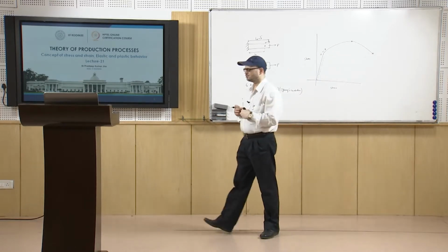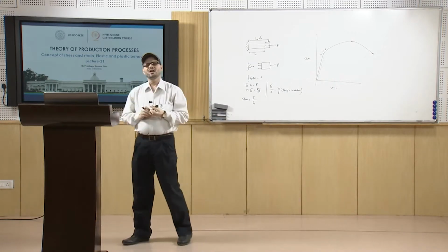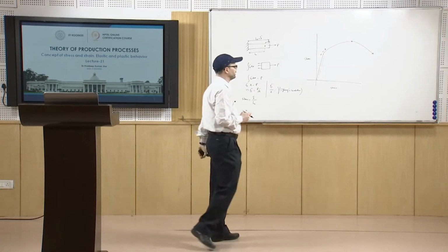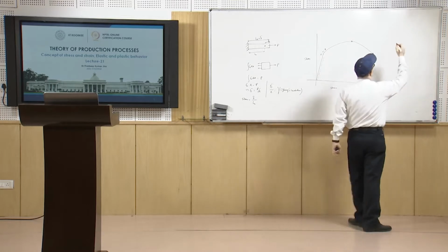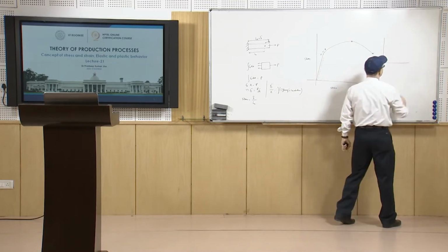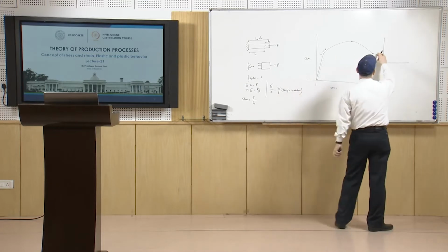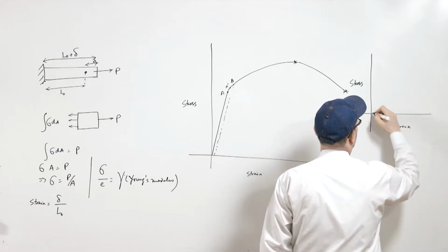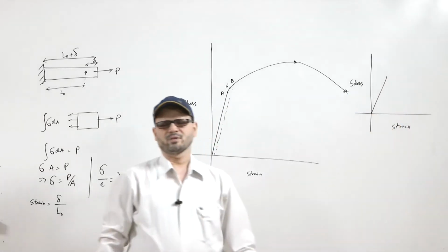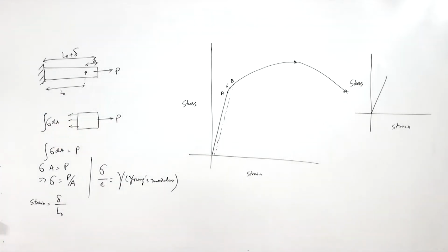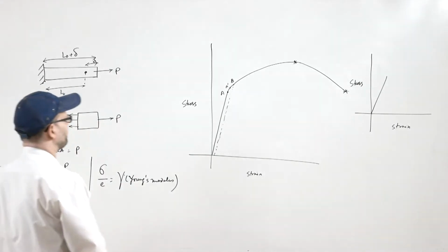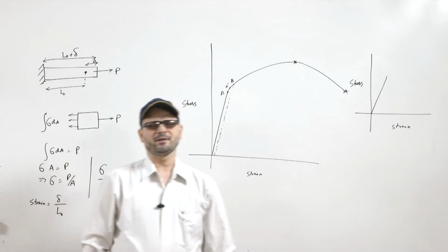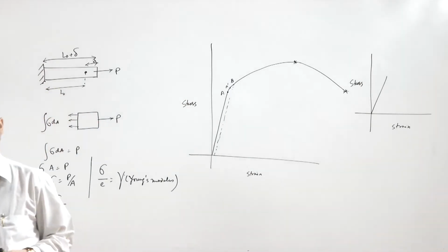Now, you may have different types of materials, and this is for ductile material. Now, you may have a brittle material. In the case of brittle material, the stress strain curve is different. Here, if it is completely brittle, this will be the curve. So, for an ideally brittle material, there is no appreciable deformation or remaining strain, and the material will fail without any appreciable deformation.